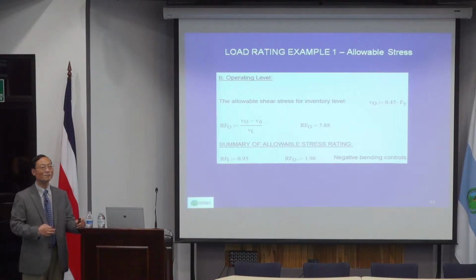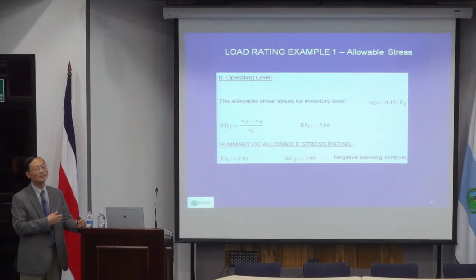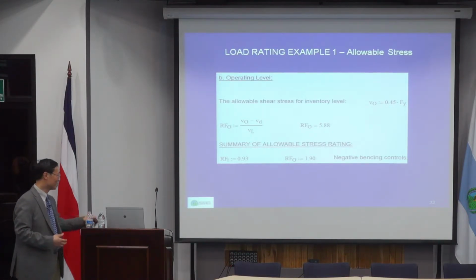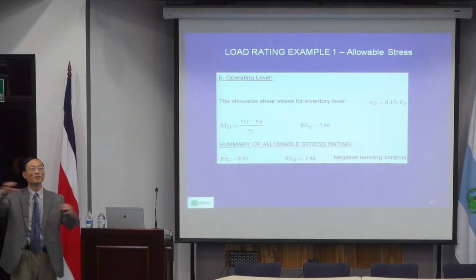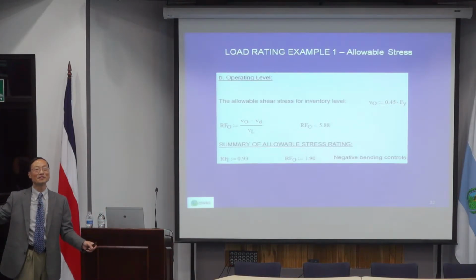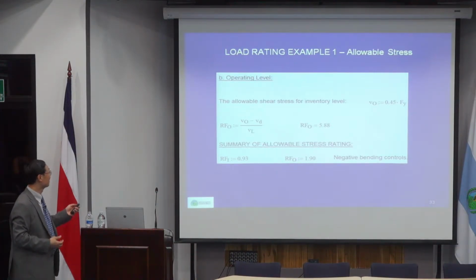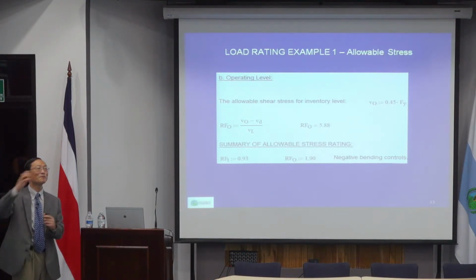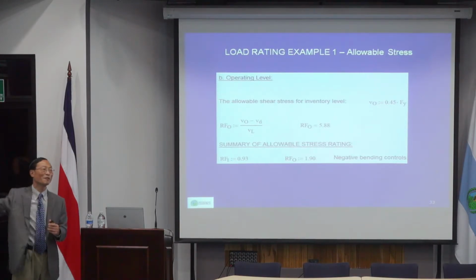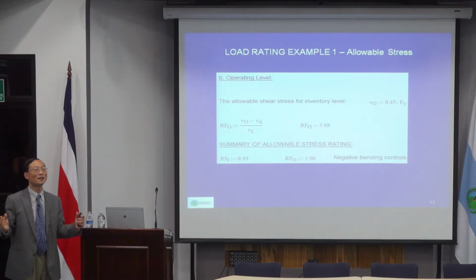The purpose of load rating, again, is for determining if the bridge is safe enough, and also for selecting candidates for rehabilitation. For example, if we have a rating list for any selections, you want to select the one with a poor rating. That's globally. Individually, if you see a bridge like in this case and you want to select it, probably you want to strengthen the negative bending areas. If you are replacing the deck, probably you can put more reinforcement in the deck over the piers to increase capacity.